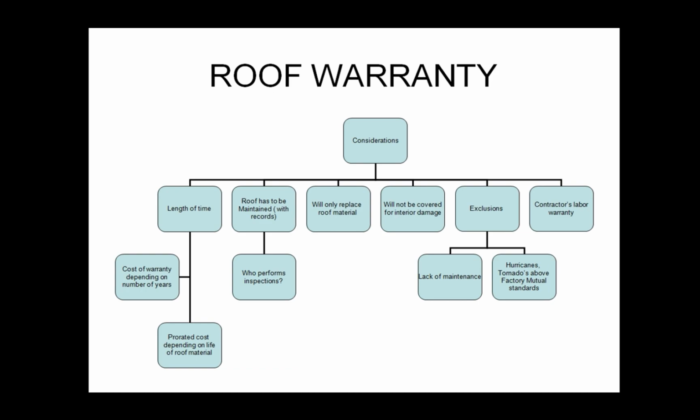All right, but some of the considerations, again, know the fine print. Okay, not only is there a length of time, but sometimes these systems require maintenance, proof of maintenance as well. So you may have to have the manufacturer come in and do an inspection or witness the maintenance as it takes place. You'd have to probably have a maintenance plan and other things showing how you will perform the maintenance on those roofs. Warranties sometimes only replace the material, doesn't cover the labor. That's another thing you have to look for.